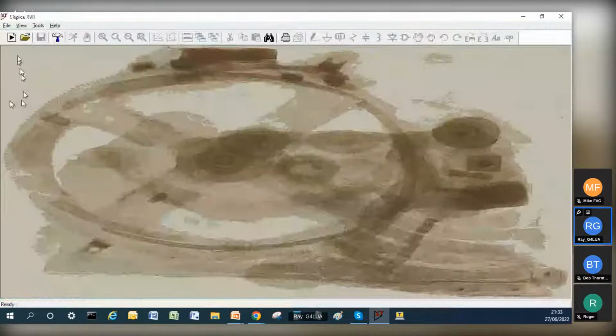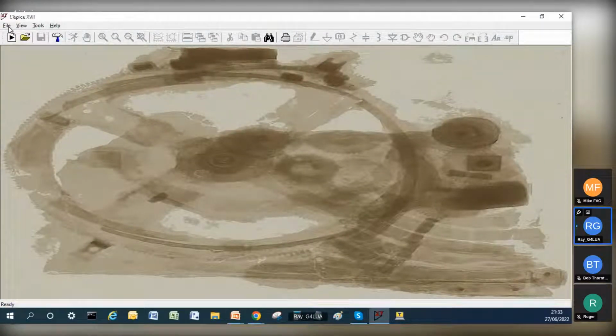Is the file just a numeric text file that gives you max and minimum values and a time step? Right, so it's just a sample? So if you wanted to generate a staircase waveform, you would generate a time step, an amplitude, a time step, an amplitude, a time step, an amplitude. And then when you incorporate it, you could put repeat. Effectively, you tell it what the coordinates are. Yeah. I don't know if I can find it. Let me just have one more go.